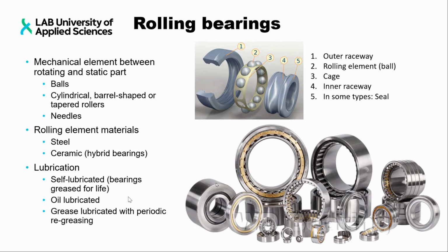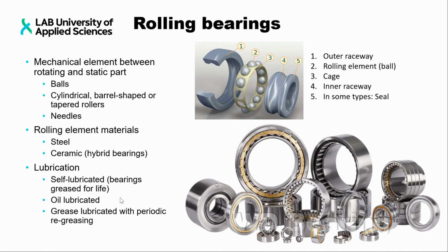Then there could be oil lubrication, especially in the cases where you need to somehow also get rid of the heat due to the contact. So in those cases, oil lubrication is being used, and also with very high speeds where grease is not anymore an option.